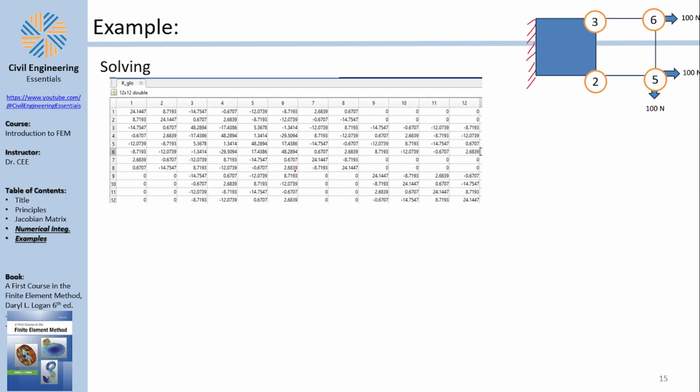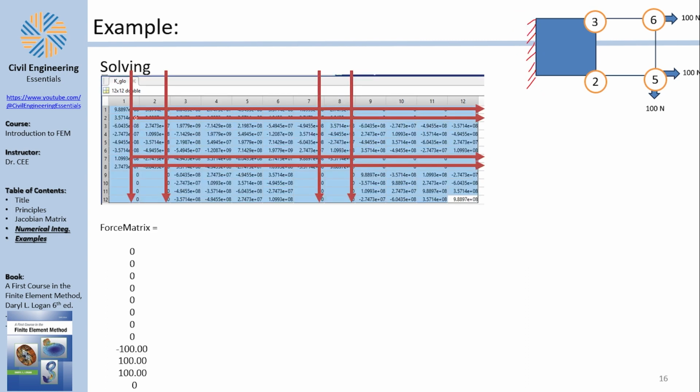Fantastic. Now here, of course, the end is nearing, because now all you have to do is solve the stiffness matrix. I put here some supporting conditions, meaning there is no movement in U and there is no movement in V for node number 1 and node number 4, meaning that you're going to slash and dash the U1, V1, U4, V4 in both lines.